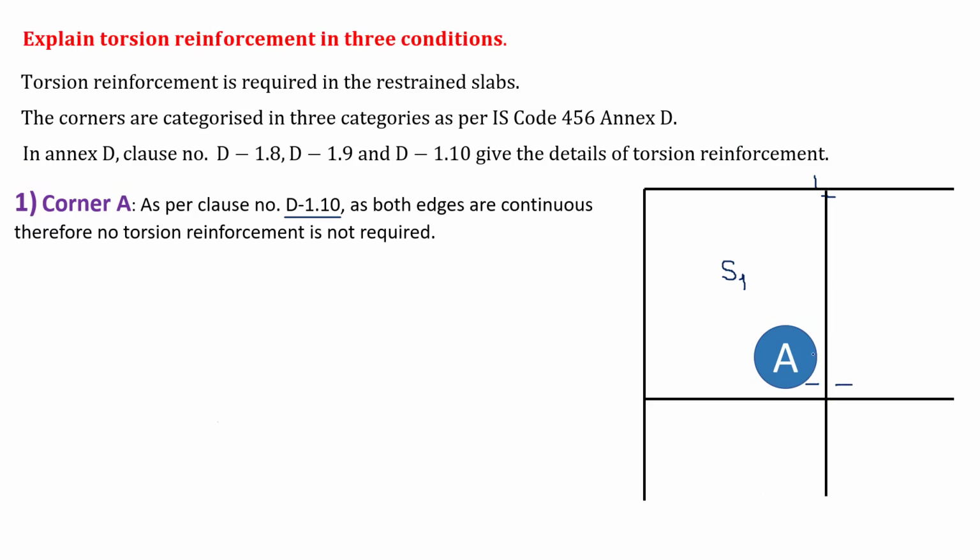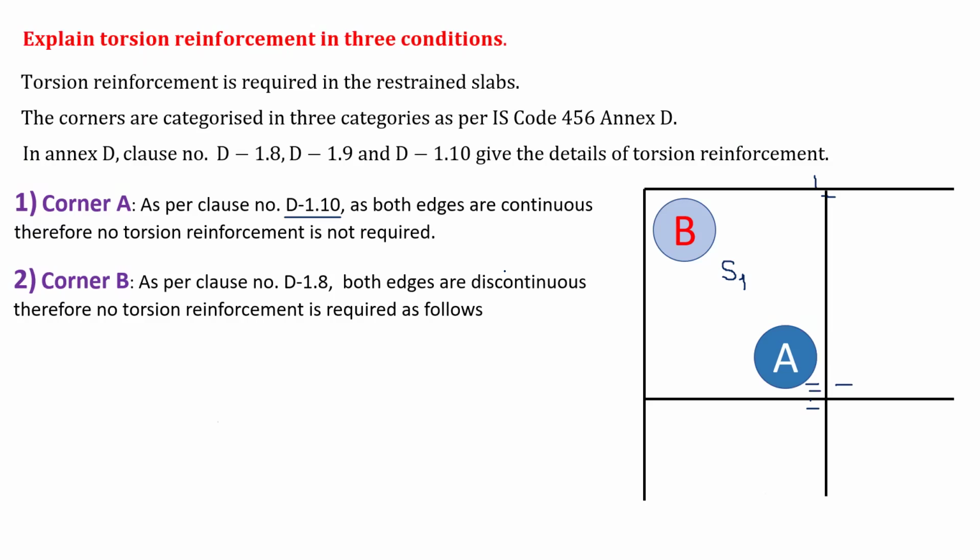Similarly, for this edge, it is balanced by this edge, so there is no resultant torsional moment here, and therefore we need not provide any torsional reinforcement.